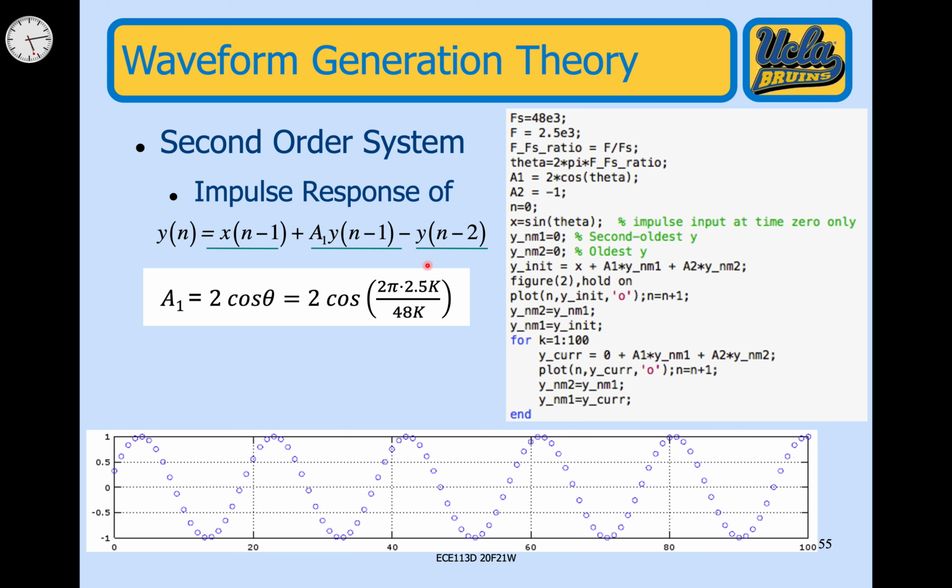So what you do is you write a little code. Now this is a MATLAB example, and you can't do it like this in your embedded system, but this gives you the idea of it. Here's your sampling rate, and all this kind of stuff. You're simulating it actually. I'm calling it theta, which is equal to this value, 2 pi f over fs.